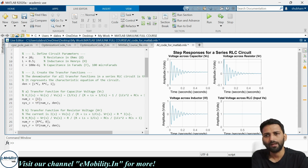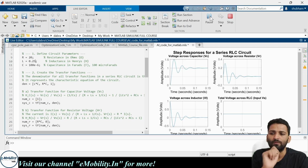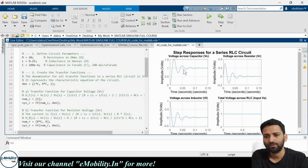For this I don't need code. You can do this by AI also, but because I understand coding a bit, I know these are the circuit parameters, and I will change them here only. I will reduce this to 0.25, and these are the new values. Now I will update and see the impact on the response. Because I have increased the resistance, the oscillatory nature of the circuit has been reduced. This is one of the typical examples.